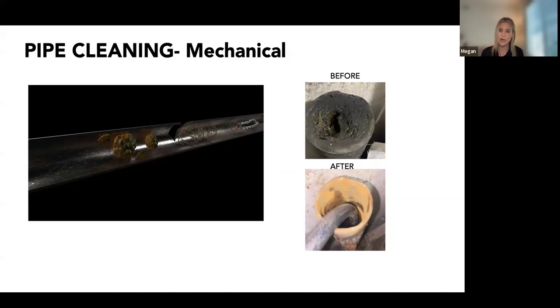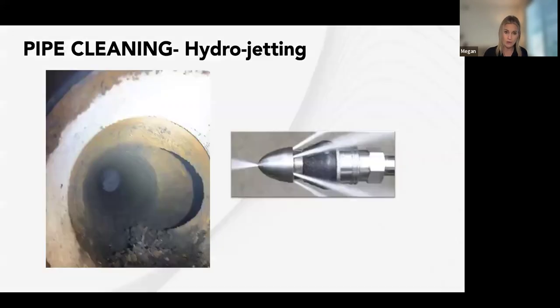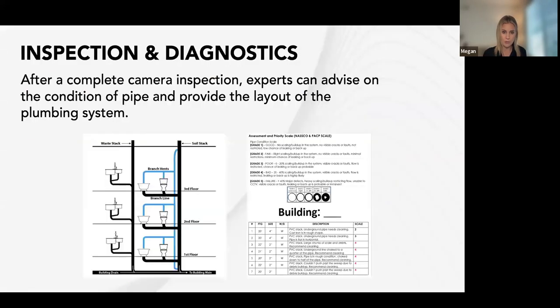We'll provide recommendations and typically if the property is coming up on the end of their life, we're probably going to recommend complete lining for everything. So you have a 100% lined pipe, new solution, new system. Or if we have to replace some of those branch lines and we have to open up walls because they're short, we might do a hybrid solution. But we can definitely give options.